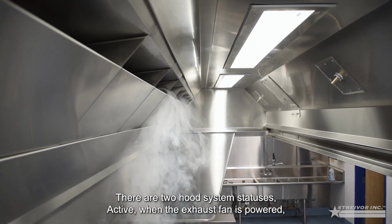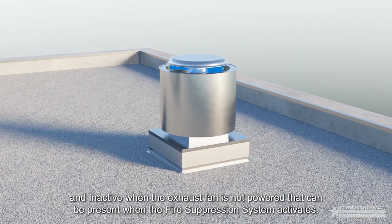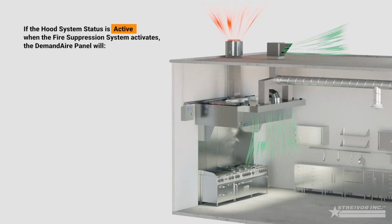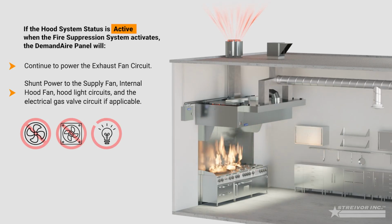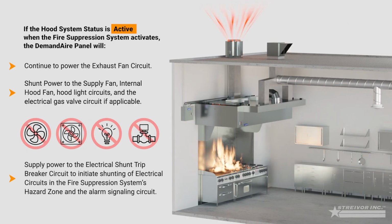There are two hood system statuses: active, when the exhaust fan is powered, and inactive, when the exhaust fan is not powered, that can be present when the fire suppression system activates. If the hood system status is active when the fire suppression system activates, the DemandAire panel will continue to power the exhaust fan circuit and shunt power to the supply fan, internal hood fans, hood light circuits, and the electrical gas valve circuit if applicable. Supply power to the electrical shunt trip breaker to initiate shunting of electrical circuits in the fire suppression system's hazard zone and the alarm signaling circuit.